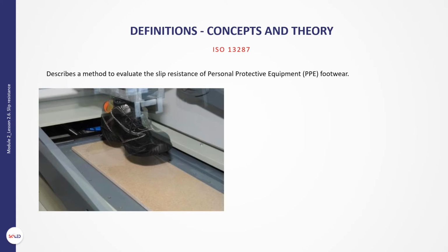The footwear shall be tested in one or more of the following modes. 1. Forward heel slip at angled contact. 2. Backward slip on the forepart. 3. Forward flat slip. The heel test mode is considered to be the most important in relation to reducing the risk of pedestrian slip. The footwear can be tested on different floors and conditions, for example, ceramic tile floor or steel floor with a specific soap solution or glycerin. This test can also be performed on an ice floor or other that we would like to test for a specific application.